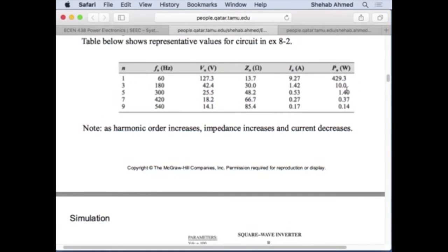In a resistive load, you will get real power. But a motor does not operate in that fashion. A motor, if you don't supply it with a 3-phase balanced load, meaning only the fundamental component, what happens is these 3rd harmonics and 5th harmonics, they will cause heating because they are actually torques, but in the opposite direction. So the way we would,